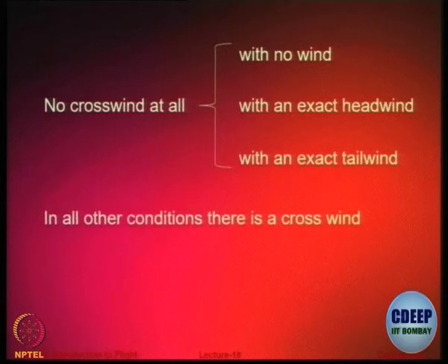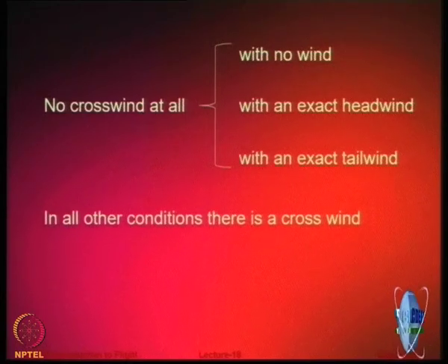So if your stalling speed is 90 knots, you can land in 30 knot crosswind. If the crosswind is 50 knots and Vstall is 90 knots, you are not supposed to land. You are supposed to abort the landing, as we will see in some examples.